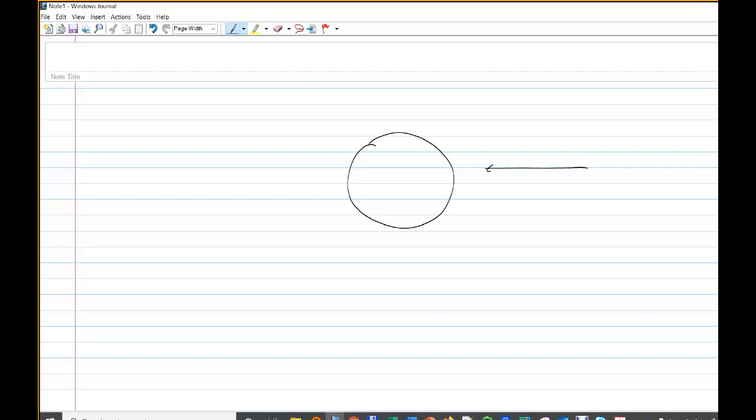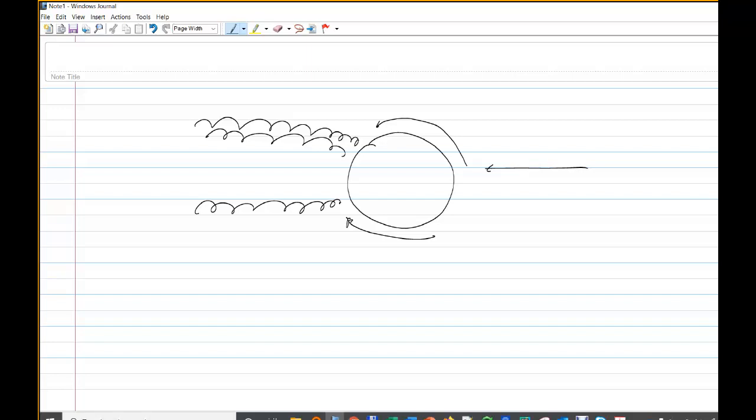So the fluid is coming in this direction and it actually cannot follow exactly the contour, and it's going to get detached here. This detachment causes these vortices and this turbulence. And one interesting thing is that with time, that's what you have, this vortex shedding or von Karman vortices, this detachment point can change. For example, it can be here, up here, or down here, and it becomes a cyclic oscillatory problem. So when this one detaches here, that one is detaching up here, but then when this one is detaching up here, this one is detaching here.